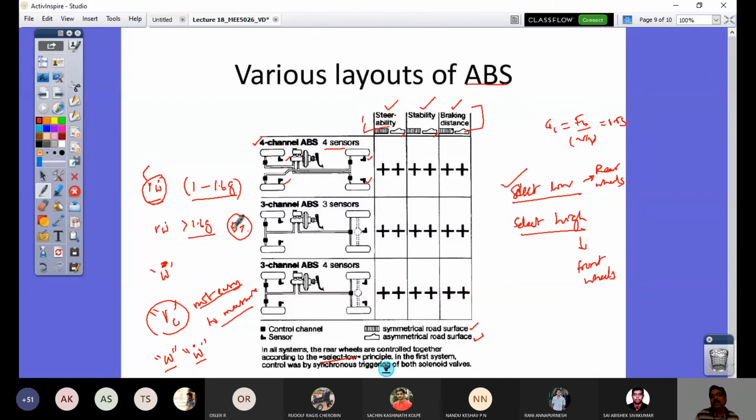There will be a sensor for that. You can measure the vehicle deceleration at its CG location by mounting a sensor. If this is achieved, then again it will give an instruction to increase the brake pressure. That means applying the brake. Again it will compare, by applying the brake, what is happening. If the deceleration rate is more than this, then that cycle would be repeated.